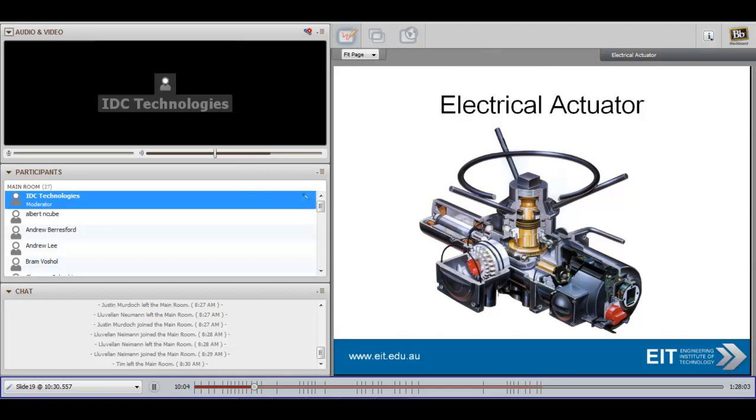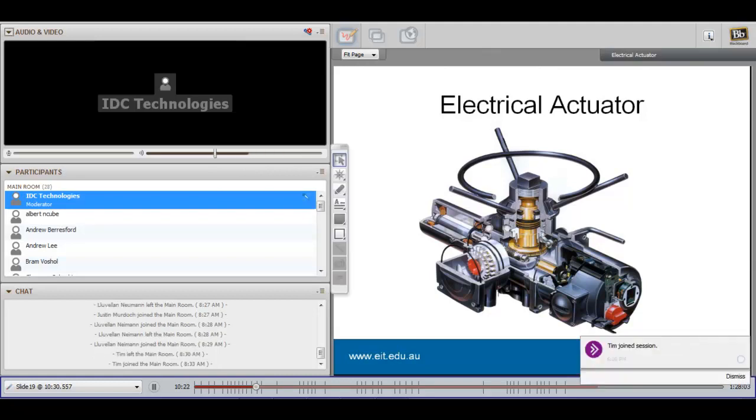Still pretty slow in certain applications. They don't always have a fail-safe action. They're not extremely good for modulating control. They can still be a bit expensive, and they most certainly are going to be difficult to maintain. You're also not going to consider using these devices in explosive areas because of the risk that you run when you have the elevated voltages that are going to be present.